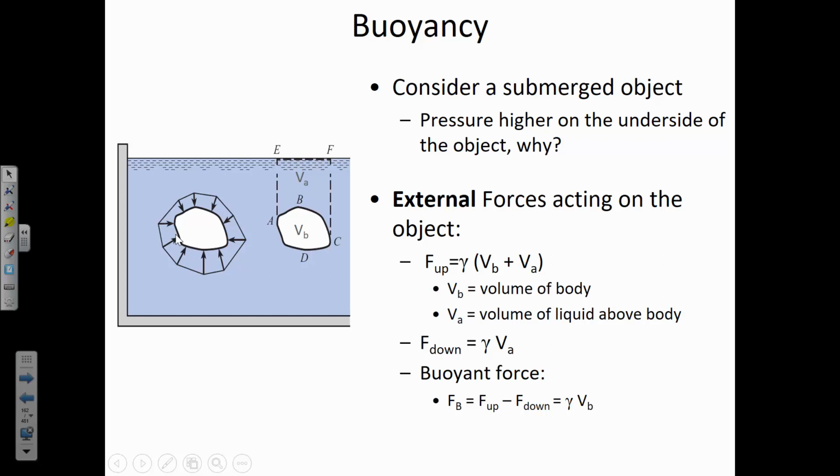And this goes back to the idea from last time where we had a tank of water like this. Here's the water level, and then there was this irregularly shaped wall. Okay, there was like this plate, and the forces were acting upward. And what I said was, you need to extend the water line over here, and so the magnitude of the forces is equal to how much water would have been above it.